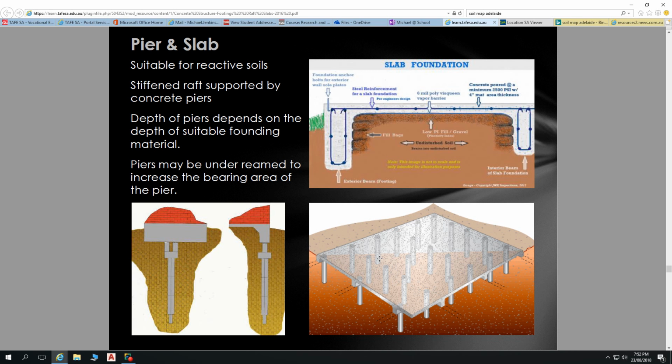Also, there are formwork sleeves that you can buy as well. You put the sleeves inside your auger holes. They act as a formwork for bringing your concrete slightly higher than the ground, which makes a very nice formwork. But it also means there's a smooth side to the top of your pier, so that earth can swell and subside without grabbing the side of your pier and trying to move your pier along with it.